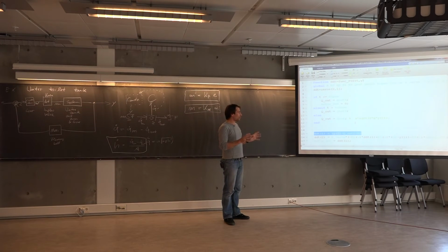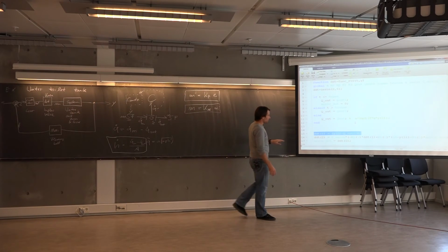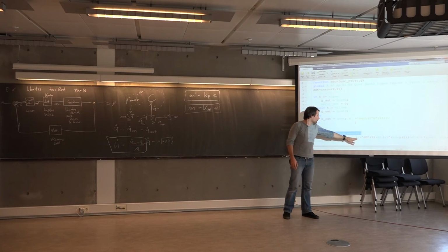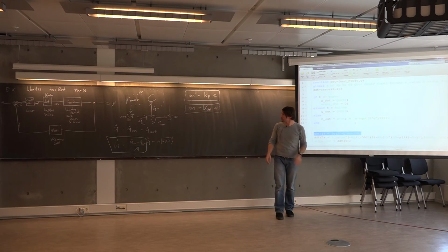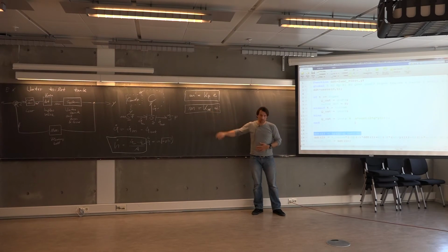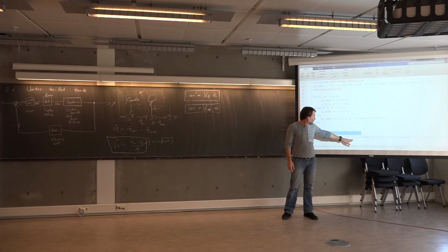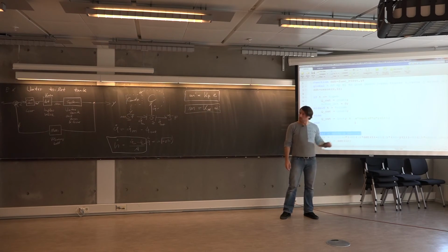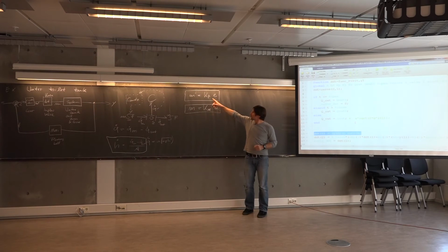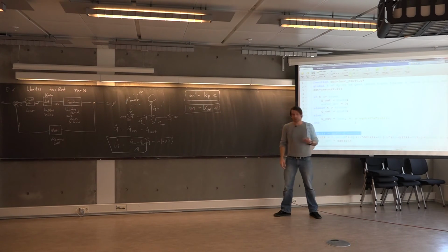Now this one looks very complex. Please ignore it just for the moment and take a look at this first term here, which is this valve coefficient, which we have introduced, times the manipulated variable, which is the first term here in parentheses, minus Kp times the error. Now here we have the derivative of the error.